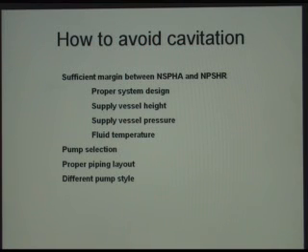If you jump to a larger pipe size and you have less friction loss in the pipe, then you'll have higher pressure at the pump suction. Yeah, but the pressure is the H rho G, but that's suction. So your installation is much more complicated. Well, you'll find as we go through the next couple slides that the velocity loss of the pumpage through the pipe is a consideration for the NPSH. Yeah, so you have friction losses in the pipe. Bigger pipe, lower velocities, less friction loss.